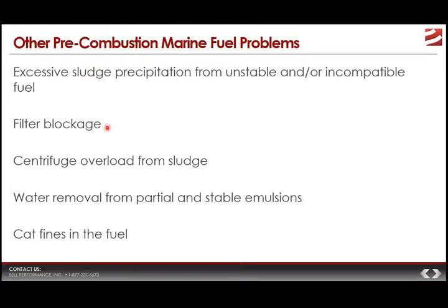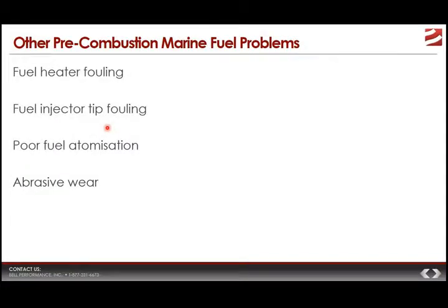So that can be a problem. And of course, the aforementioned presence of excess amounts of catalytic fines like aluminum and silicon in the fuel. Other pre-combustion problems: fuel heater fouling, and fouling of the fuel injector tips is a big one because that leads to poor fuel atomization. And of course, those catalytic fines can cause abrasive wear in the fuel pumps and the fuel injectors. So those kinds of areas can be fouled by the excessive inorganic content.